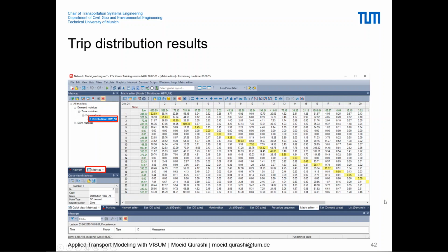But the basic idea of an OD matrix is that, using this four-step modeling approach, having zones and having OD matrices, we cannot actually represent the trips that are within one zone, because we are not certain how many people are going out within one zone for walking, biking.